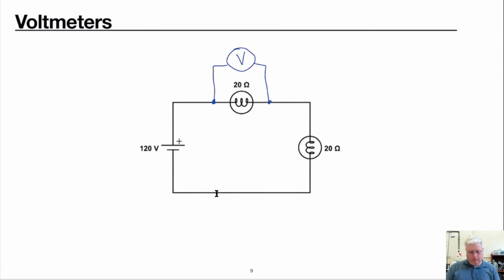So in reality, what this would actually look like is you would have your voltmeter, which nowadays is in something called a multimeter, where it has a combined voltmeter, ammeter, a meter to measure resistance, and some other things. And so it has two prongs, with wires connecting to it, and you just touch it around the device you want to find out about, and then you can actually read what the voltage drop is across that device.